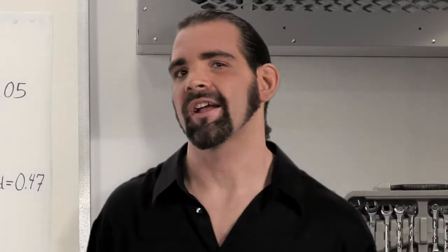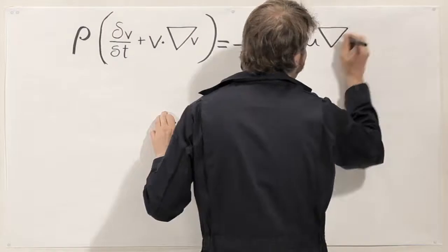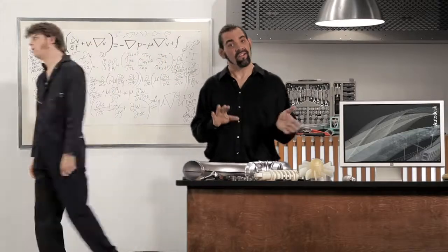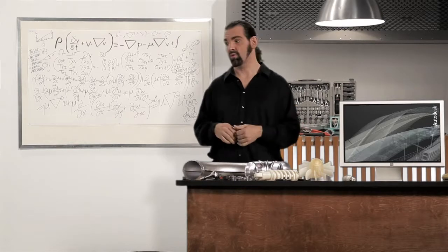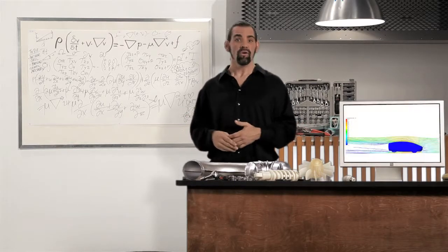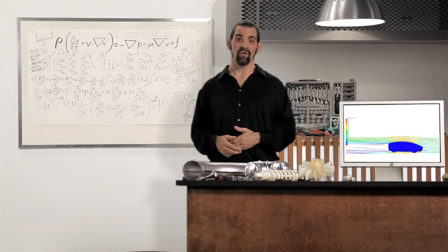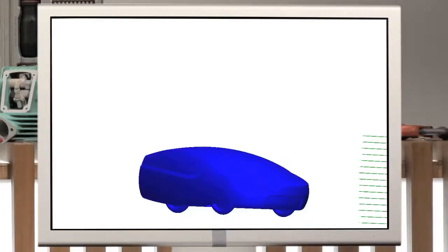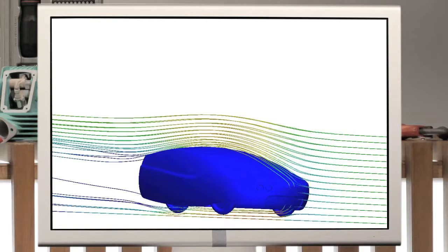You can determine the drag coefficient of your design using the Navier-Stokes equation, but that can be impossible to solve with pen and paper. So you'll have to calculate it experimentally in a wind tunnel, or use an estimated value, or use computational tools to do the math for you. Most cars have a drag coefficient of about 0.3, while a streamlined car might have half that.